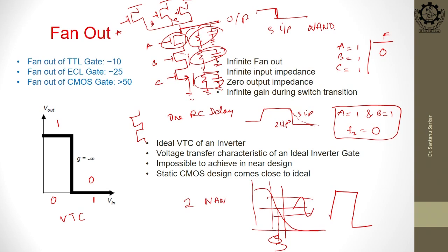So, even this VTC will satisfy the VTC of an amplifier, because in this zone my transistors are in saturation, right. That is why the slope is so high, it will jump quickly. But ideally this range is so narrow, it is not suitable, isn't it?